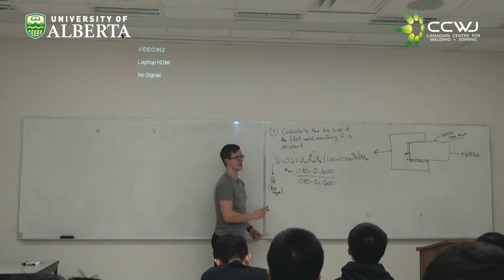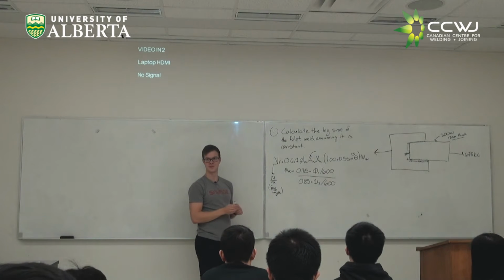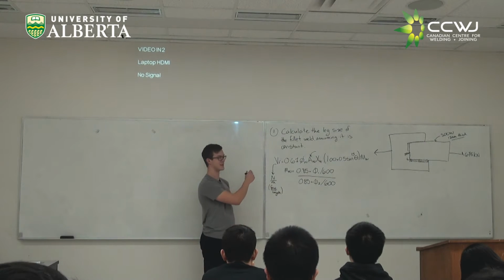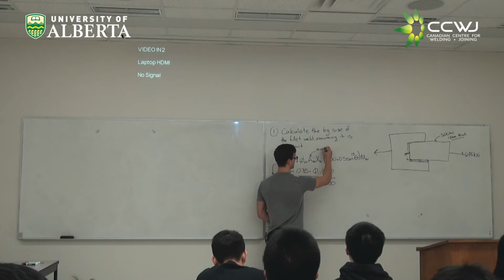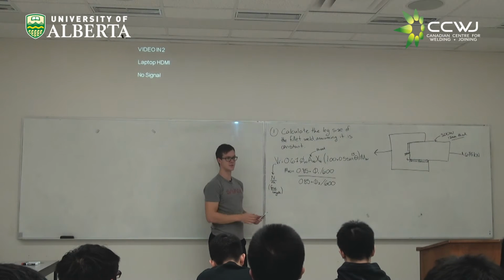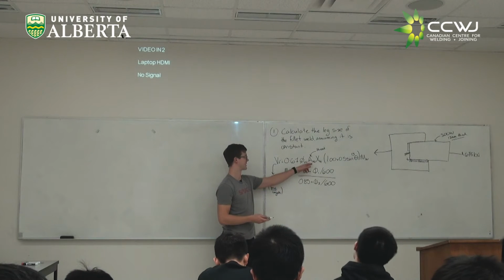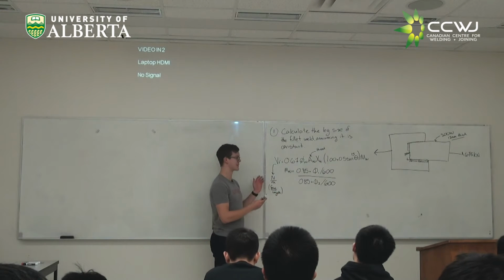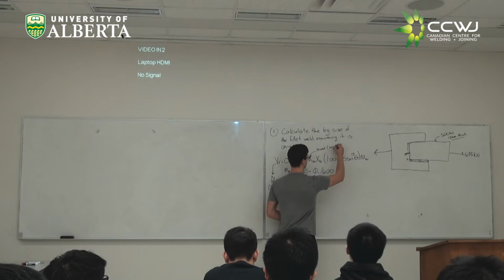Does anyone remember what units our A_w has? Meters or millimeters? Right, so this is one of the interesting things with the way we've done this. A_w ends up being our throat, right? So it's not an area, it's not millimeters squared. That's one thing that sometimes catches people, because if you didn't have it fresh from class, you're looking and thinking this is supposed to be an area, and you start adding things in where you're not expecting them, and suddenly your dimensions don't match. So this is the throat, so this is just length.